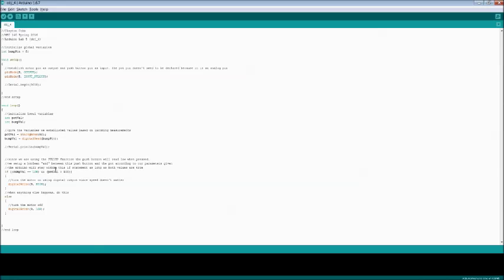So what this is saying is that when the bumper switch is pushed and the potentiometer value is above 500, do whatever's inside. If the bumper switch wasn't pushed but the potentiometer is above 500, it's not going to execute it, and vice versa.